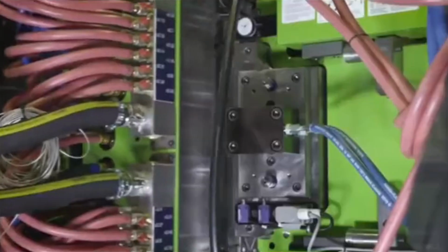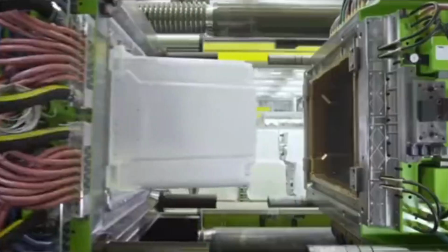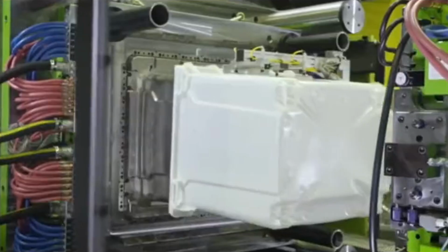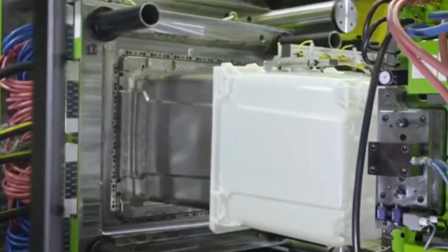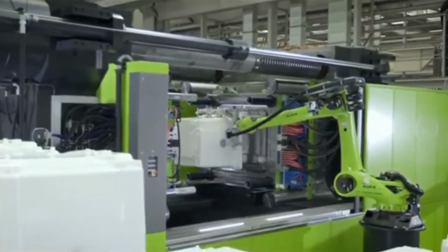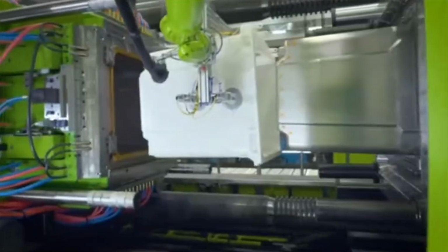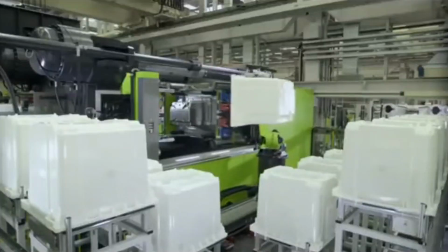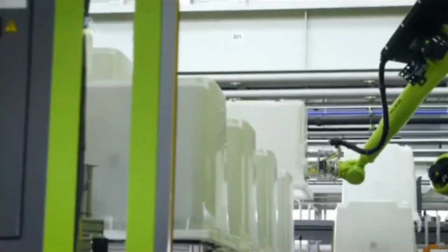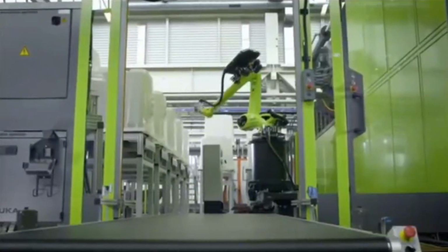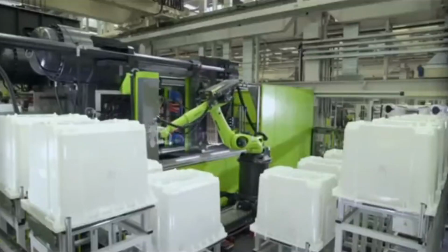Setting injection parameters, including injection pressure, injection speed, holding pressure and time, cooling time, and so on. The injection pressure is used to inject the plastic melt into the mold cavity. The injection speed affects the filling effect of the plastic. The holding pressure and time are mainly used to replenish the volume loss of the plastic in the cooling contraction process, and the cooling time determines the demolding quality of the plastic product.